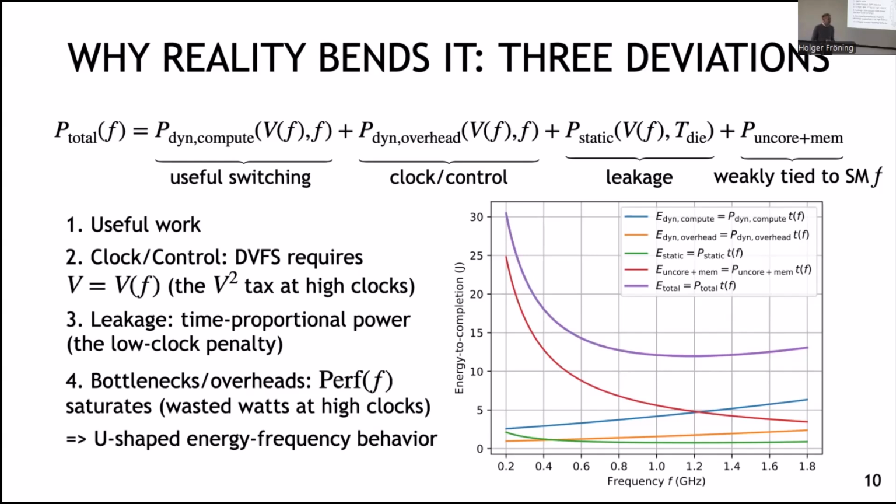And this was a point in time where I stumbled over the comment that race to idle is possibly your most important friend when it comes to being more energy efficient. So manufacturers tell me, do things as fast as possible. You burn plenty of power, but time will be your friend, so you will consume the lowest energy. This figure tells me that the reality should actually look different. But of course, it all depends on the practical aspects of the processor at hand. And this will be the second part of today, where we're going to explore in a little more detail if we see some similar effects when it comes to DVFS tuning for LLM workloads.